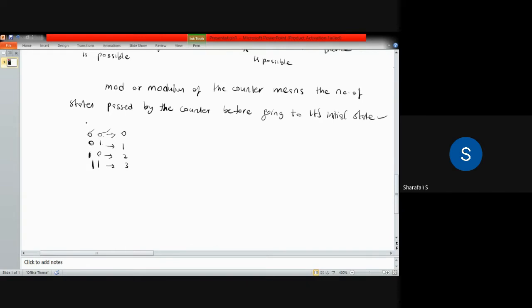So this is your first output, for example Q0, and this is your second output, Q1. This is the output of the first JK flip-flop, and this is the output of the second JK flip-flop. So we need two flip-flops to store these values. Each time, the first flip-flop stores this 0 and the second flip-flop stores this 0, and you get a total value of 0. So the counting will be 0, 1, 2, 3, etc.